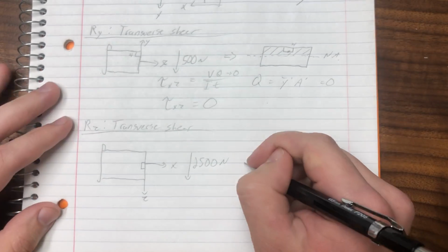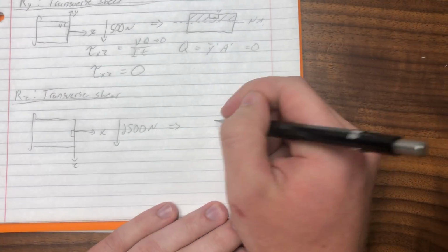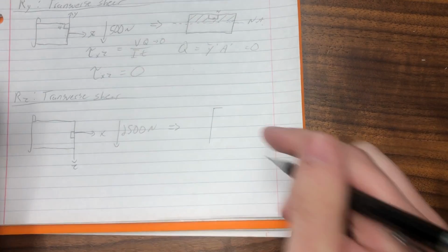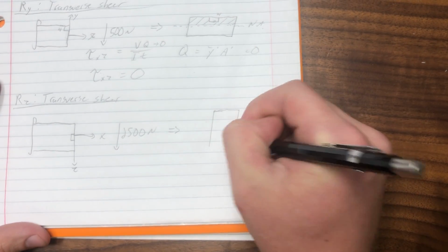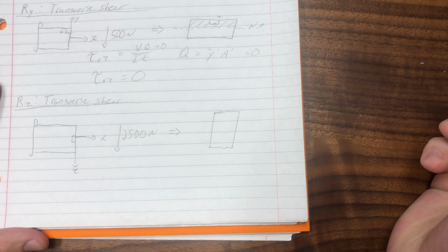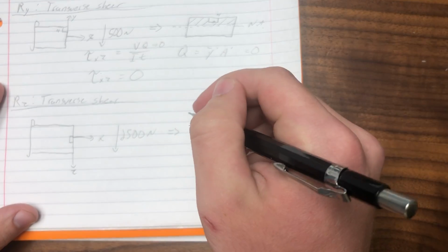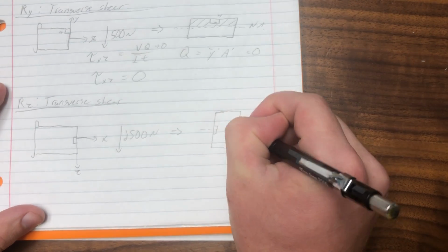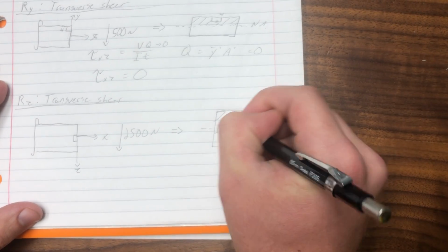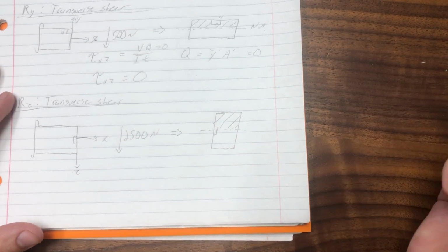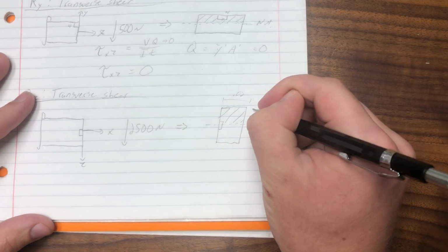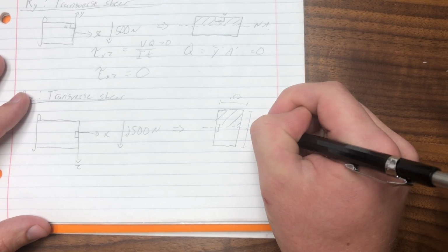And you got to flip it again. So this one, it's actually going to look like this, like when you rotate it towards you. So the shape will be like this, this will be here. Your neutral axis will run right through here again, and this will be the area you're looking at. So that'll be your outer area. This is 0.02 meters, and this is 0.04 meters.